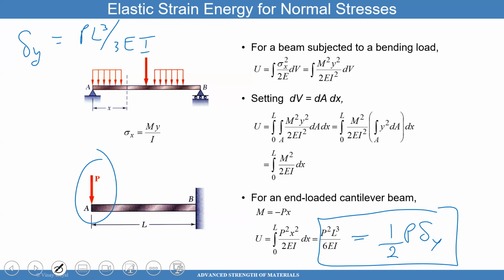I don't understand what that means, but I can tell you this. I apply the load downwards, so the deflection is measured downwards. If I apply the load upwards, then the deflection is measured positive upwards, in this example. But you can choose your sign convention. That's a beautiful thing about energy. Does that make sense? Can somebody Google for me the deflection for cantilever beam under load applied?